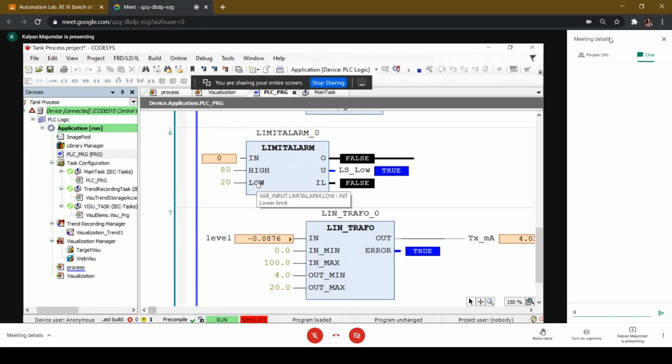Remember, you've got two level sensors. One is a lower level sensor in the upper tank, and one is a higher level sensor in the upper tank. Okay. Now, where you locate them, that's your choice. You can locate them at 10%, 90%, 20%, 80%. It's your choice. You decide. So, when the liquid level is below the lower sensor, the output is 0.